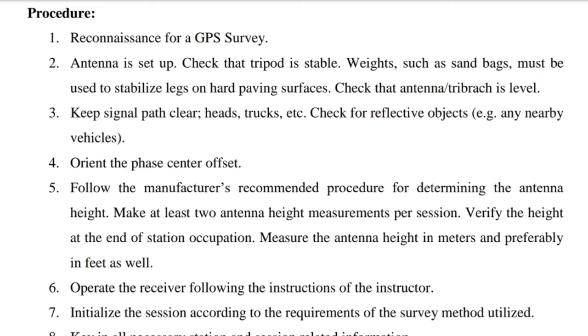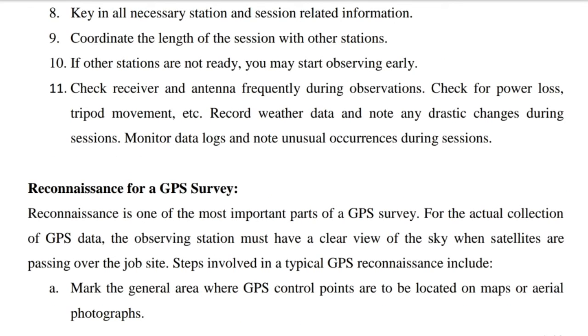6. Operate the receiver following the instructions of the instructor. 7. Initialize the session according to the requirements of the survey method utilized. 8. Key in all necessary station and station related information. 9. Coordinate the length of the session with other stations. 10. If other stations are not ready, you may start observing early.